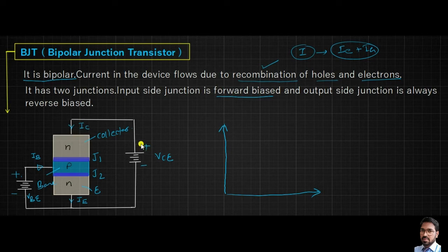from this positive terminal, plus. We can show it in the symbol of BJT, and here the current flows like this, IC, and IE is grounded and it is the IB. So this current flows when we maintain the base emitter voltage here, but it is the actual current that goes into the device.